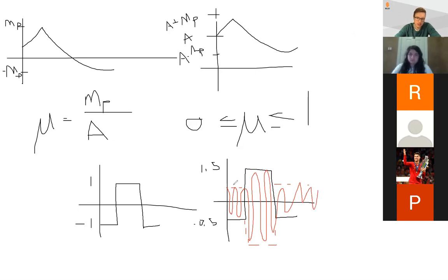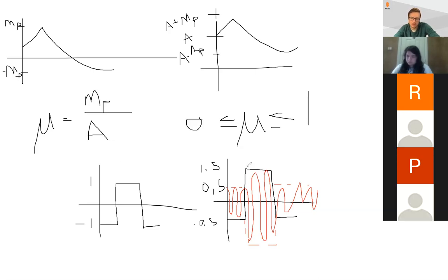Now this does not contain the exact shape of the original envelope. The original envelope went from -1 to 1, whereas this one goes from 0.5 to 1. But if we had a very sensitive receiver, we still might be able to detect the difference between these two pulses, but it's just not guaranteed to be distortionless.